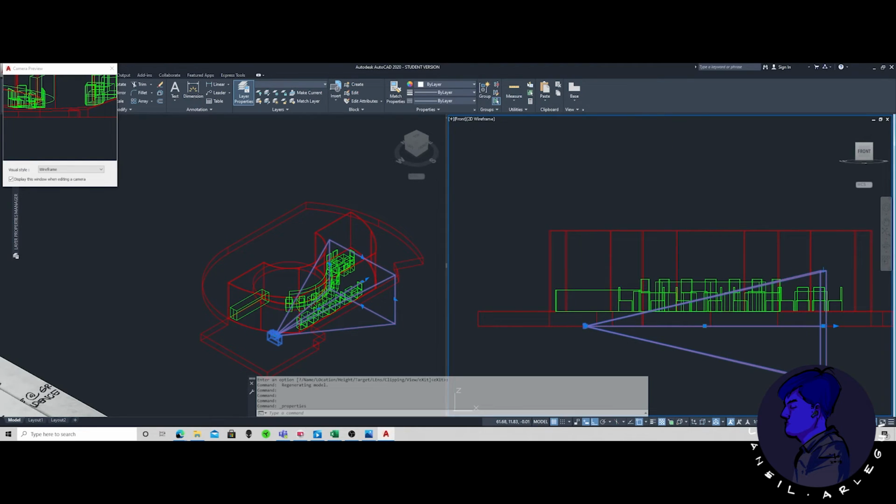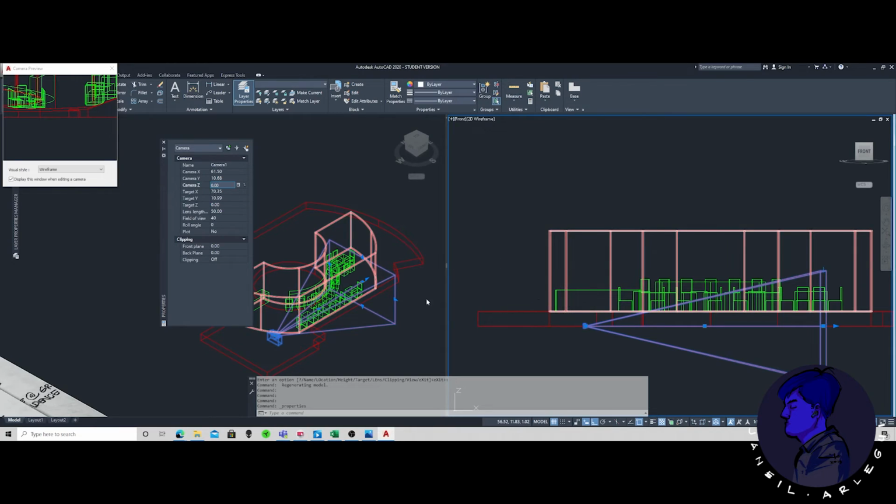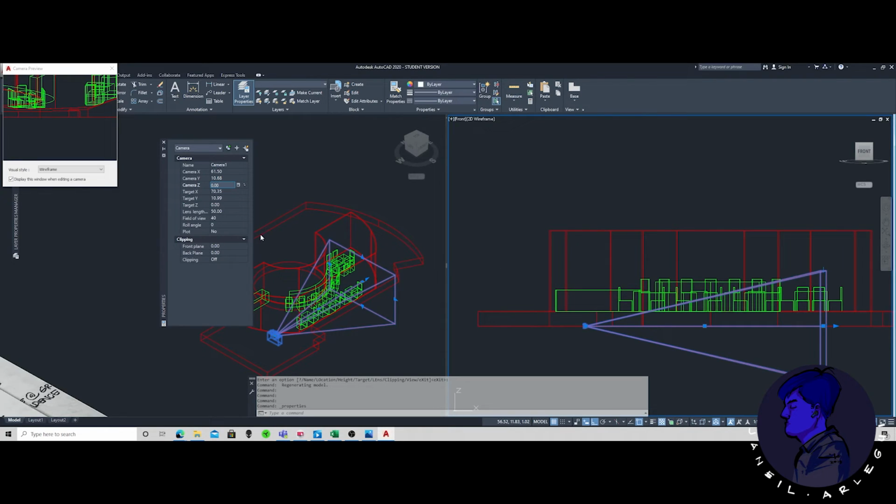So in order to do that, I'm going to go and tweak the properties. Okay, so the property box is just right clicking it, click the camera, and then click here, and then you get these values. So what I need is the Z camera. It's going to be 1.5 plus 0.55, which is the surface from the 0, would be 2.05.